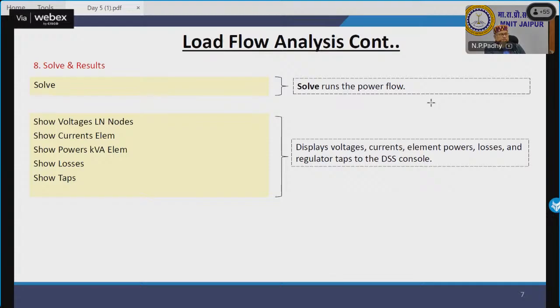Okay. So the voltage solution has nothing to do with whether it is islanded or grid connected. You again have to assume a bus as a PV bus, because that islanded microgrid will have some generating sources. So that will be your slack bus, and we can proceed.